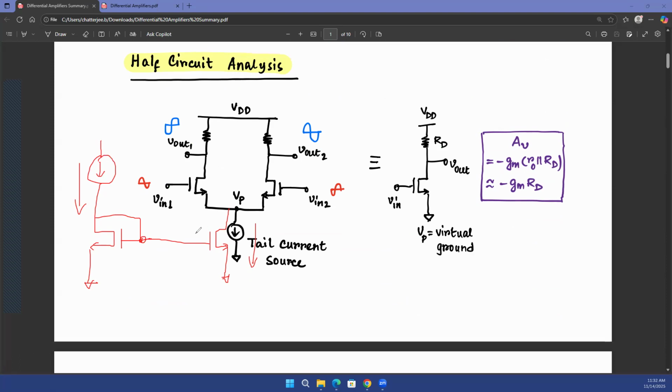Because again, if you are talking about voltage biases, voltages can always have noise, or they can have IR drop. Let's say I don't have this left side circuit, and I'm connecting a voltage source over here. Even though we say that the resistance looking into the gate is infinitely large, there is always some amount of leakage through the gate.